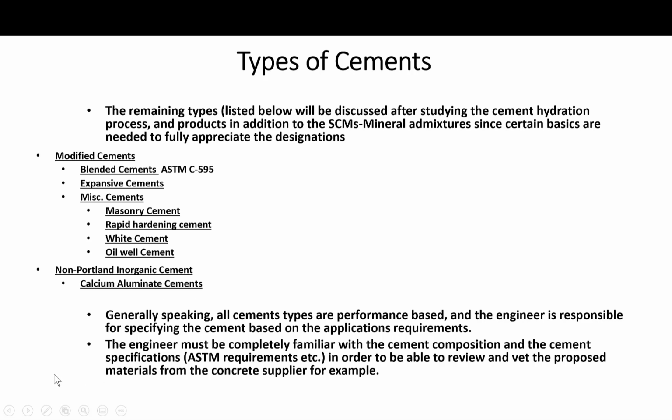As I mentioned again, generally speaking, all cement types are performance-based, and the engineer is responsible for specifying the cement based on the application's requirement. The engineer must be completely familiar with the cement composition and the cement specifications, ASTM requirements and other requirements, in order to be able to review and vet the proposed materials from the concrete supplier, for example. This is a must, in my opinion.